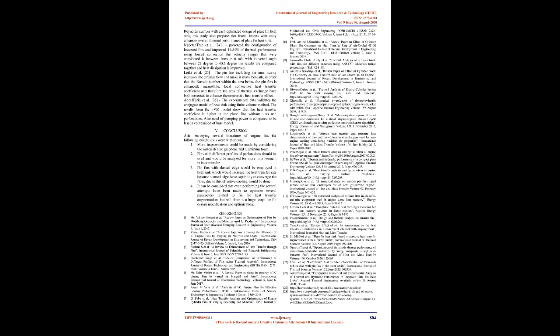Conclusion. After surveying several literatures on engine fins, the following conclusions were drawn. 1. More improvements could be made by considering materials like graphene and aluminum foam. 2. Fins with different profiles of perforations should be used and analyzed for more improvement in heat transfer. 3. Pin fins with slanted edges would be employed in heat sinks, which would increase the heat transfer rate because slanted edges have the capability to converge the flow. Due to this, effective cooling would be achieved.